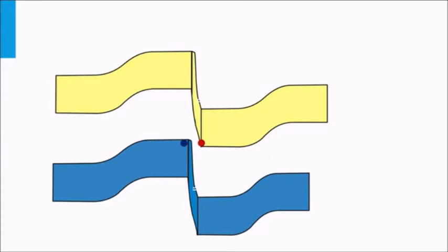The creation of such a reverse junction can be prevented by the inclusion of a so-called tunnel junction. It provides a low electrical resistance and has a high bandgap to prevent any parasitic absorption losses. The high bandgap tunnel junction is relatively thin. It means that the valence band at one side is lined up with the conduction band at the other side of the tunnel junction. The depletion zone of such a junction is extremely narrow. As a result, the slope of the valence band and conduction band are so steep that the electrons from the n layer tunnel through the small barrier to the p layer, where they recombine with the holes.